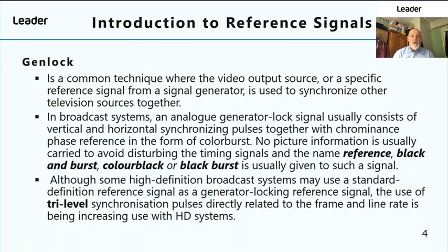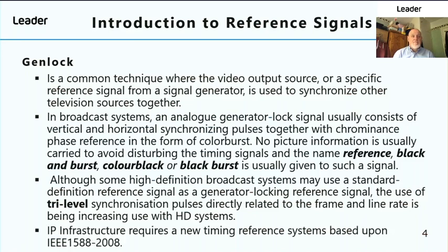And although some high definition broadcast systems may use a standard definition reference signal as a generator locking reference signal, the use of tri-level synchronization pulses directly relating to the frame and line rate is being increasingly used with HD systems. And now we have IP infrastructure, which requires new timing reference systems based upon the IEEE 1588 standard.